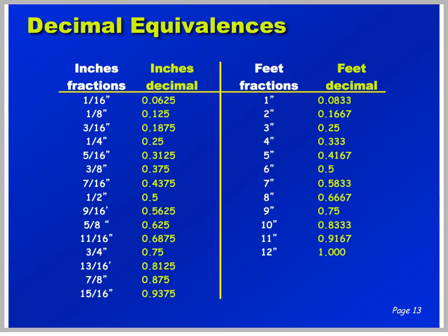Now let's talk about decimal equivalences, which are used a lot in construction. The decimal equivalence chart shown here is shown both in decimal inches and decimal feet. You cannot add decimal feet to decimal inches without first dividing the decimal inches by 12.